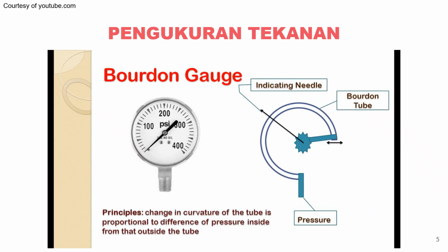So a Bourdon tube is basically a mechanical pressure measuring instrument, and thus it operates without any electrical power. Bourdon tubes are radially formed tubes with an oval cross section. The pressure of the measuring medium acts on the inside of the tube and produces a motion in the non-clamped end of the tube. This motion is the measure of pressure, and it is indicated via the movement of a needle.